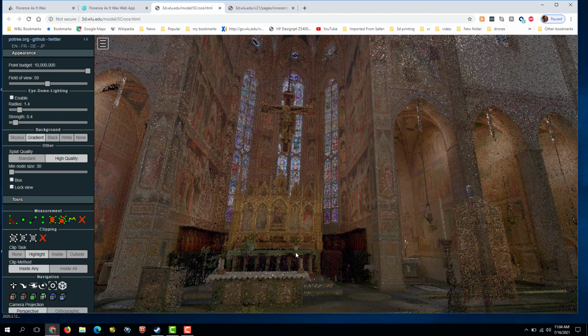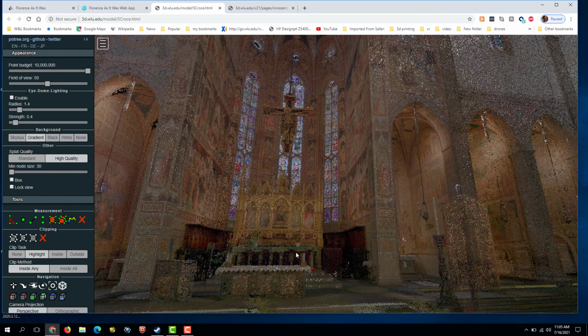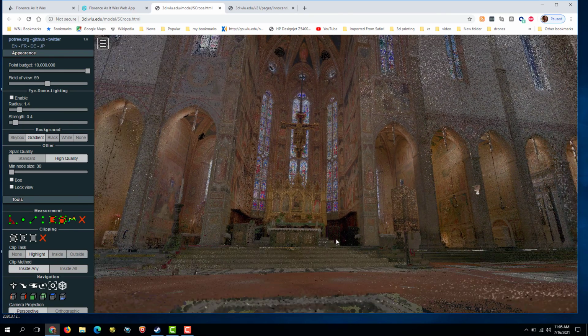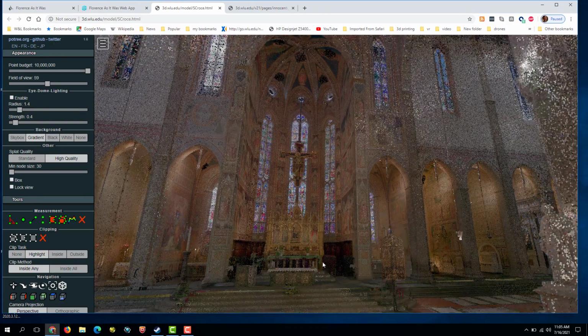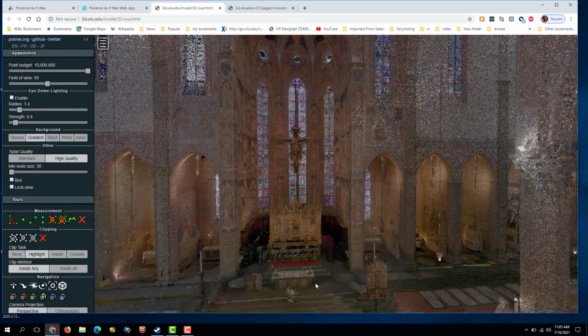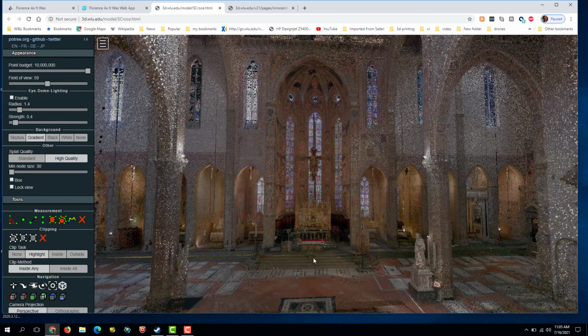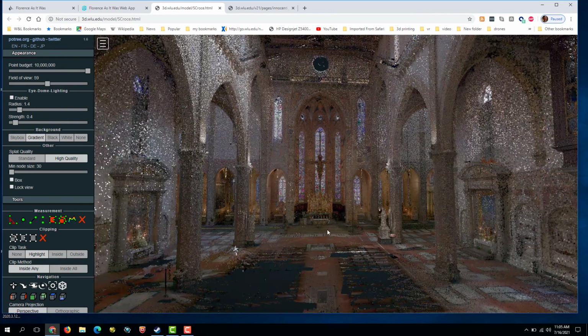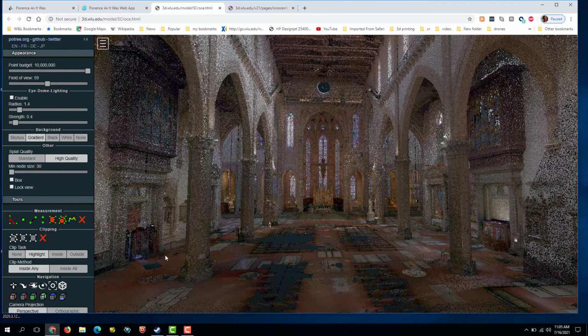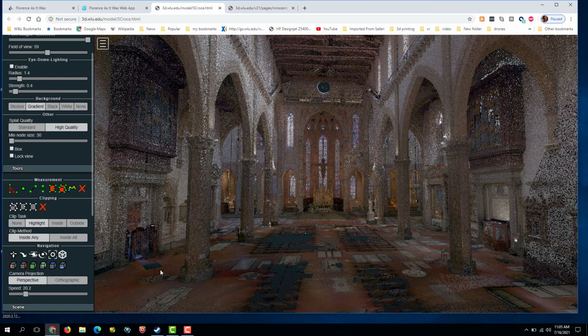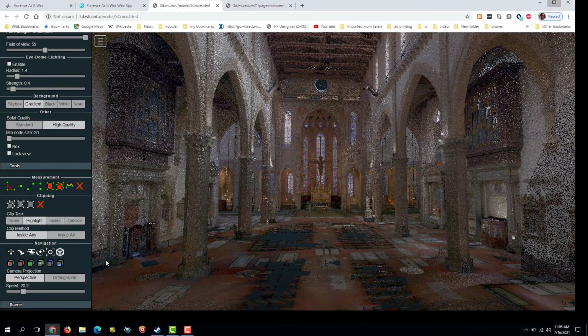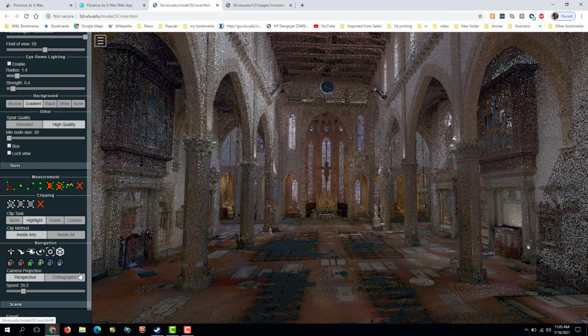Now, there are times when you want to do a tour of a facility, particularly if it's as expansive as, say, the Florentine Duomo or the complex of the Innocenti or this one of Santa Croce. Potree has a number of flying options that lets you do this with occasionally dizzying results. Now, to navigate with the flying option, move down to the menu with icons in the navigation section and click on the bird image. Now point your mouse to where you want to head at the start of your journey.